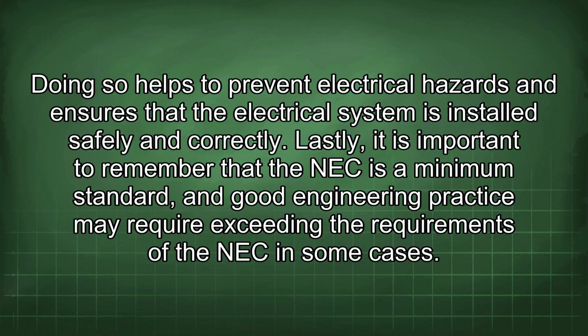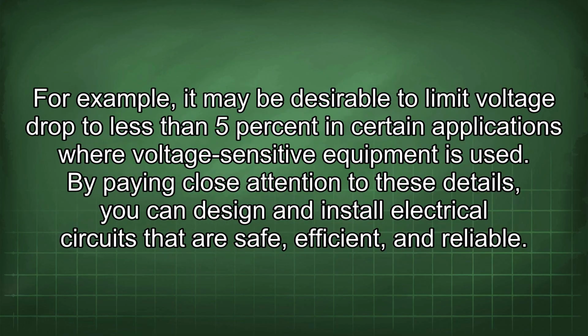Lastly, it is important to remember that the NEC is a minimum standard, and good engineering practice may require exceeding the requirements of the NEC in some cases. For example, it may be desirable to limit voltage drop to less than 5% in certain applications where voltage-sensitive equipment is used. By paying close attention to these details, you can design and install electrical circuits that are safe, efficient, and reliable.